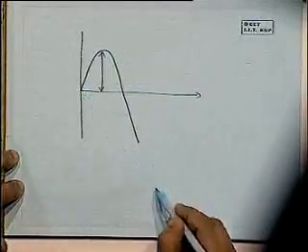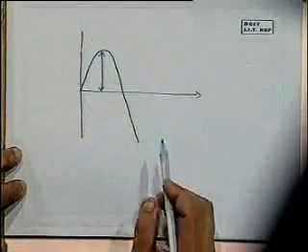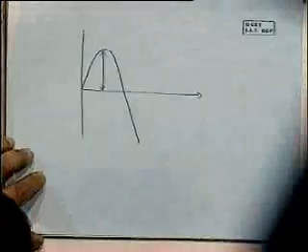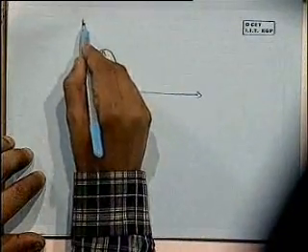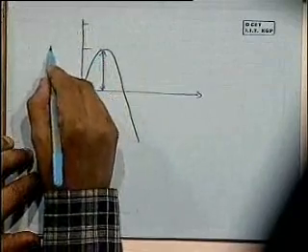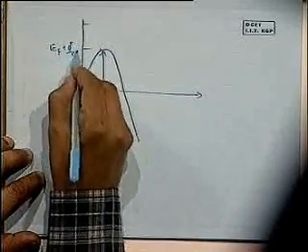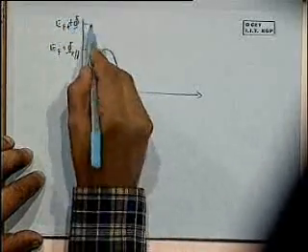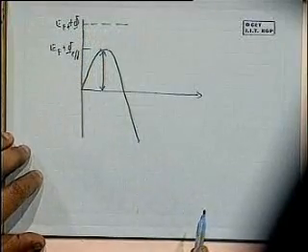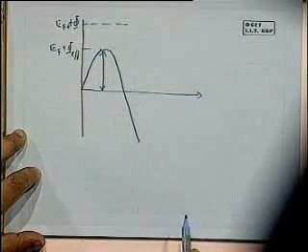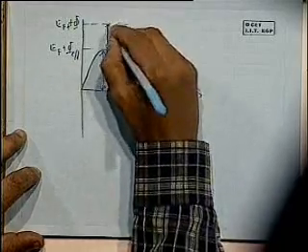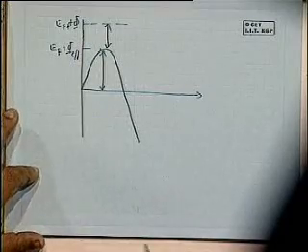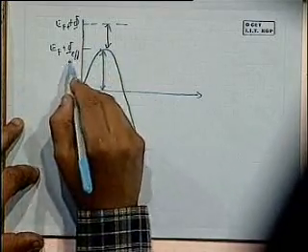I've got one force this way and one that rises to EF plus phi. And the combination of these two leaves me with an effective value. In other words, initially this would have been the barrier in the absence of accounting for the image force. Once we account for the image force, we have effectively lowered the barrier by some amount, and now the actual barrier that the electron will see is EF plus phi effective.